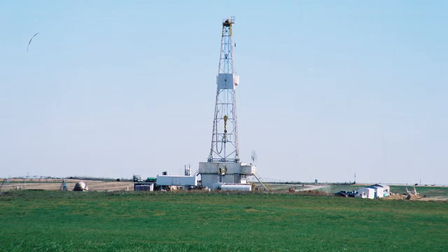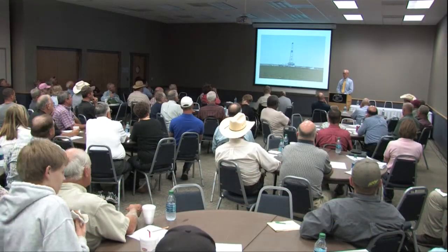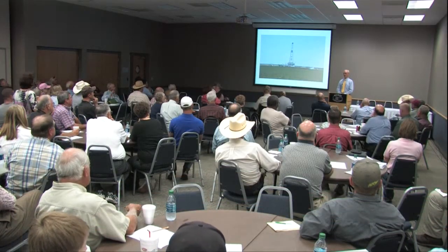They were required to have initially 2 feet of soil over the pits. Then we went to 3, and we found out that after 10, 20, 30 years, that level will decrease and we will have salts coming to the surface. So a lot of companies are going to soil farming as the answer to this.